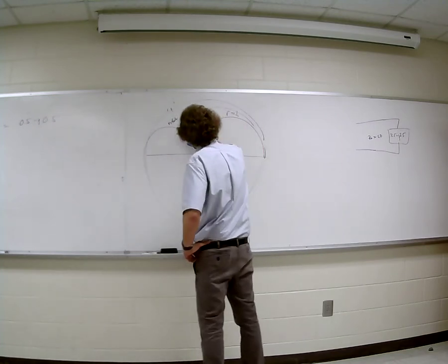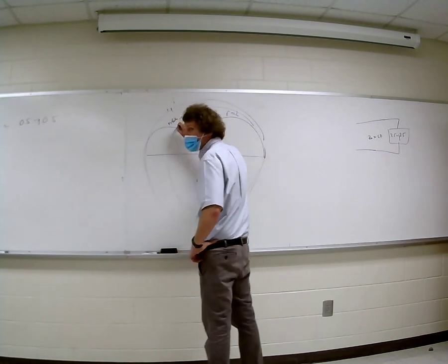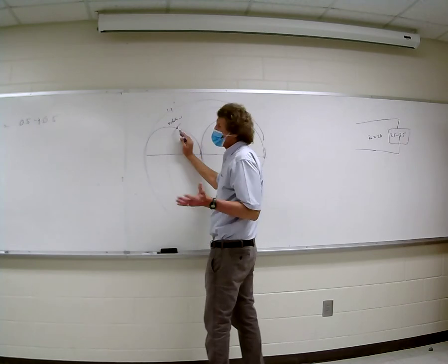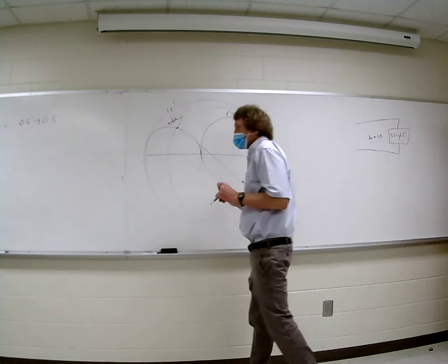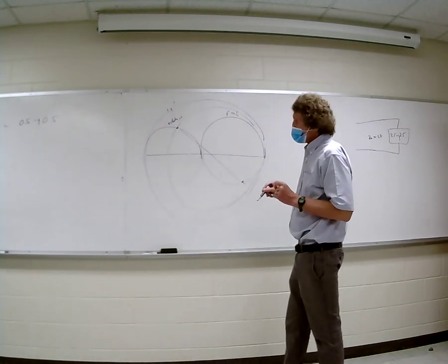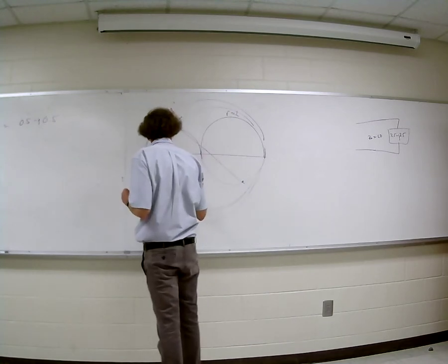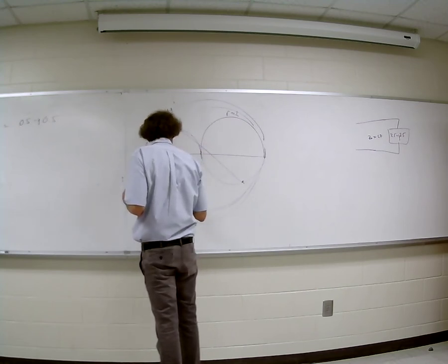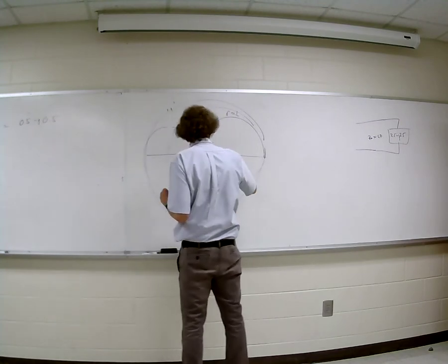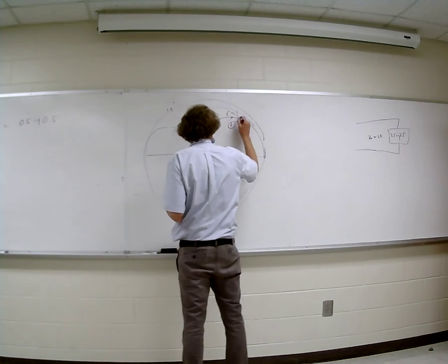Here's the thing. We just have to go to the admittance domain and go back here. Y'all follow me? If we're right on the rotated, that's ZL, right? We go to the admittance domain. What do you get for the point here? Wait a second, I drew that wrong. This is ZL down here, isn't it? Sorry, this would be 0.5 minus J 0.5. That point right there is not right. And then when we take the inverse of that, we get this point. Now we're in the admittance domain.